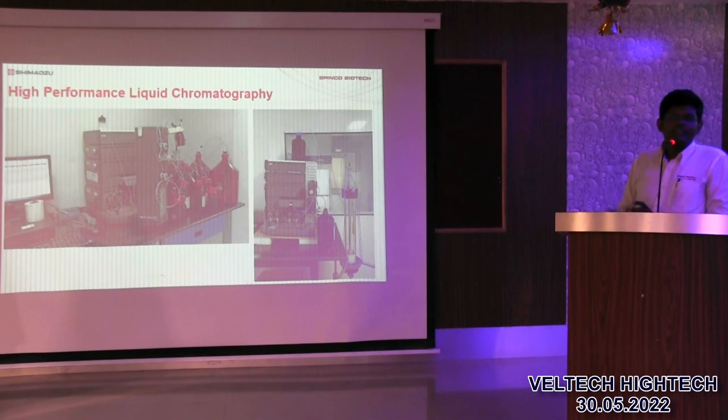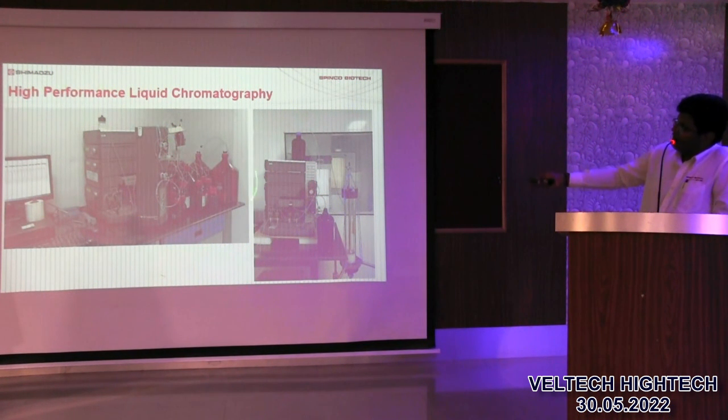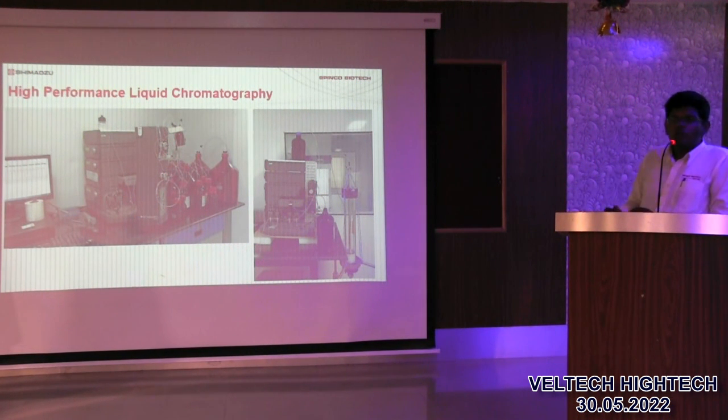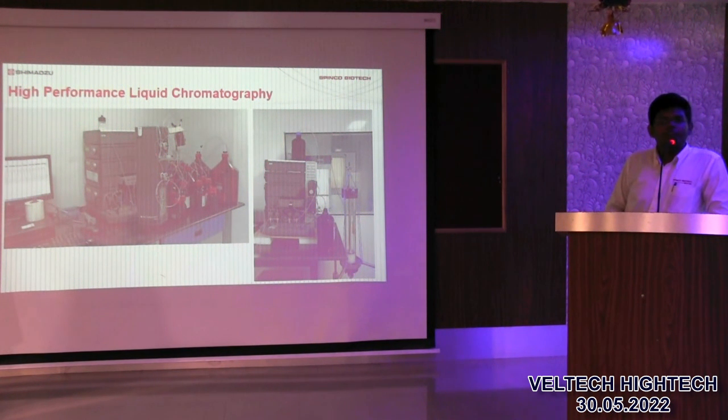Correct? In analytical scale we will have 1 ml, 2 ml, whereas in preparative scale it goes up to liters, 10 liters, 25 liters, 50 liters. That's how the scale increases. So as per the scale, they can modify the solvent. Is modifying the solvent enough? Packing material, exactly. So you should modify your packing material also.